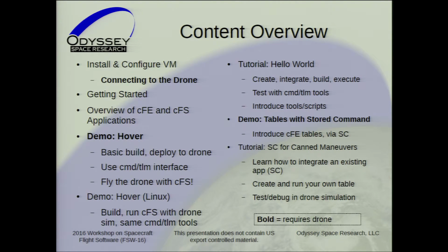We can move into the Hello World tutorial, and then we do a demo which introduces the concept of CFE tables. We use a stored command app because it's very convenient for sending different commands to the hovering drone. We show them a tutorial on how to do maneuvers, integrating an app. We give them one with SC already in there, and then a CFE installation where there's no SC, and they have to learn how to integrate the SC app. We actually give them an app checklist: here's what to do if you want to integrate an SC app. You have to worry about app IDs, performance IDs, and what to do in your make files, stepping them through it. Then they start testing and debugging on the simulation.